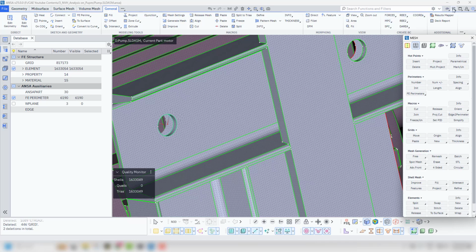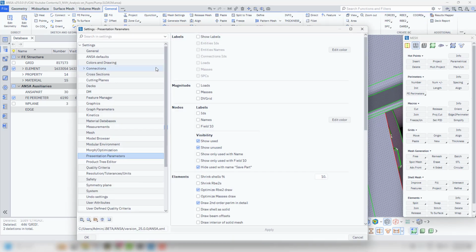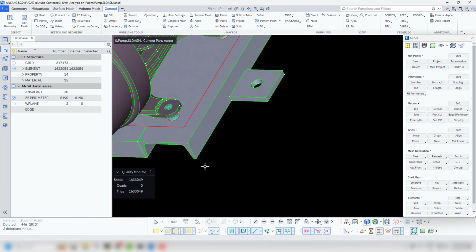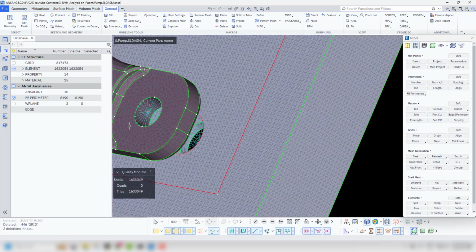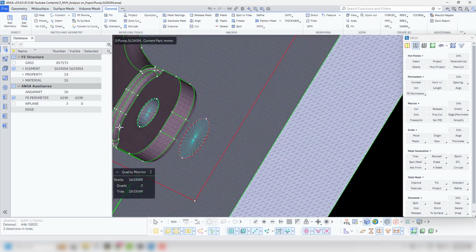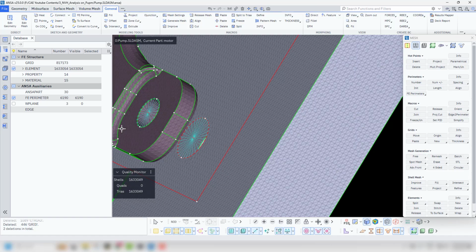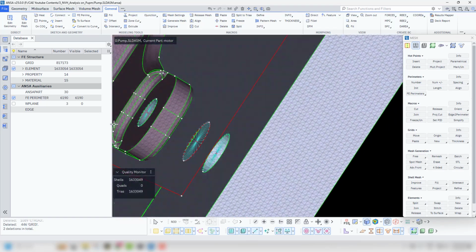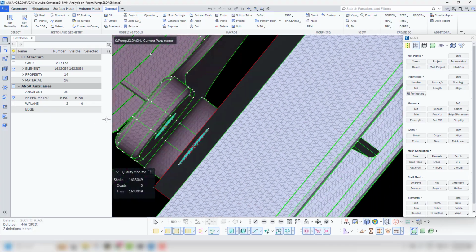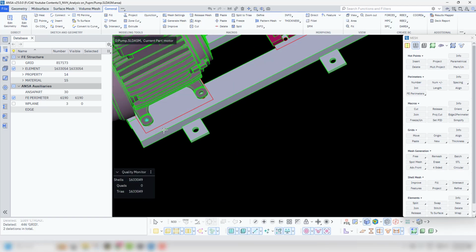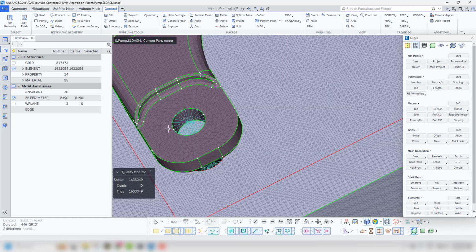Similarly, you can do it for the whole region. Before that, I would like to change the optimize RBE2. I have removed it because I would like to see how exactly the RBE2s are there. Now you can connect these with the Pbar elements and define the properties. If needed, you can also define the pretension, but right now in this session it is not in the scope.